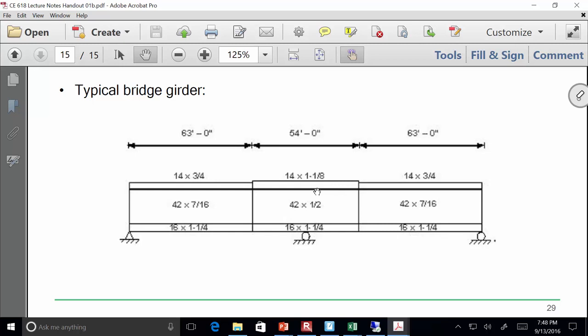In other words, if I put in a list every single positive bending region distribution factor and every negative bending region distribution factor and saw which ones were different, only about 2 or 3 would be. All the shear ones are going to be the same, all the deflection ones are going to be the same, the lever rule and special analysis, they're all going to be the same. Just the moment ones, because the moment ones only have that kg term in it.